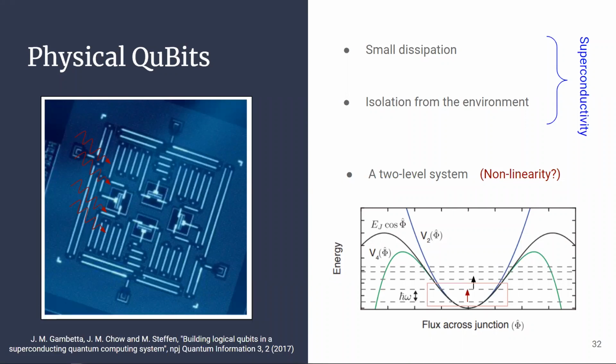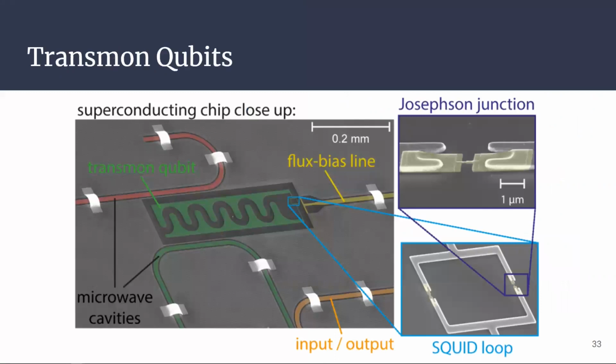and they are being used by various companies like IBM. And here we are looking at a transmon qubit. We have talked about this before, when they called it ultra small, but now we are using the term transmon here. Transmon qubits achieve their reduced sensitivity to charge noise by significantly increasing the ratio of the Josephson energy to the charging energy. So that article was on a good track when trying to understand the behaviors of these Josephson junctions.